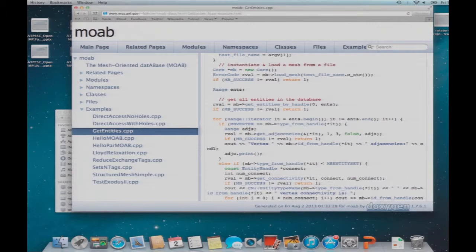When you're getting the entities for the mesh, is that something that you typically cache, or is it relatively efficient to ask for that again? It's sort of in between. It's fairly efficient to get all the entities in the mesh in the form of a range. But if you're going to use it several times in a single function, or even if you want to cache them in your application, those range objects, especially when you're dealing with large lists of entities, are fairly memory cheap. And so it's not that big a deal to cache them either, although if you're doing mesh changes later on, you can get stale lists and all that.